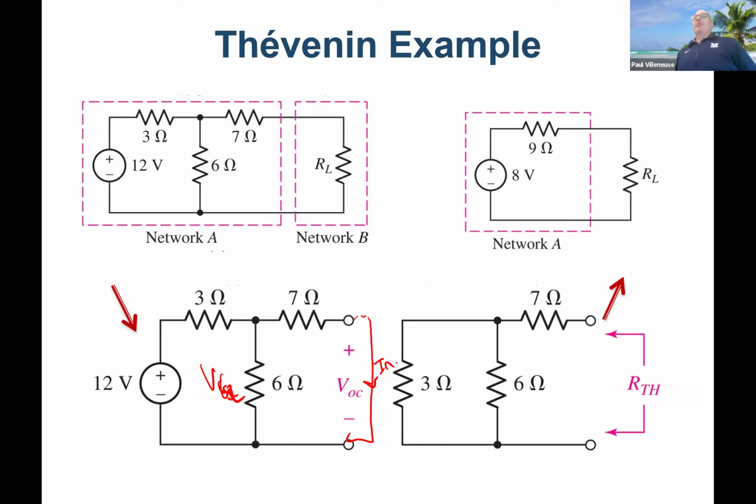But here's the nice thing about doing Thevenin and Norton. You find one, and then you can find the other one just as easily, right? Like I solved for the open circuit voltage here as the Thevenin equivalent. If I put a dead short circuit across here, I will get I Norton, won't I? That's the whole thing about having them equivalent to each other. So you can decide, is it easier to solve for V Thevenin or is it easier to solve for I Norton?